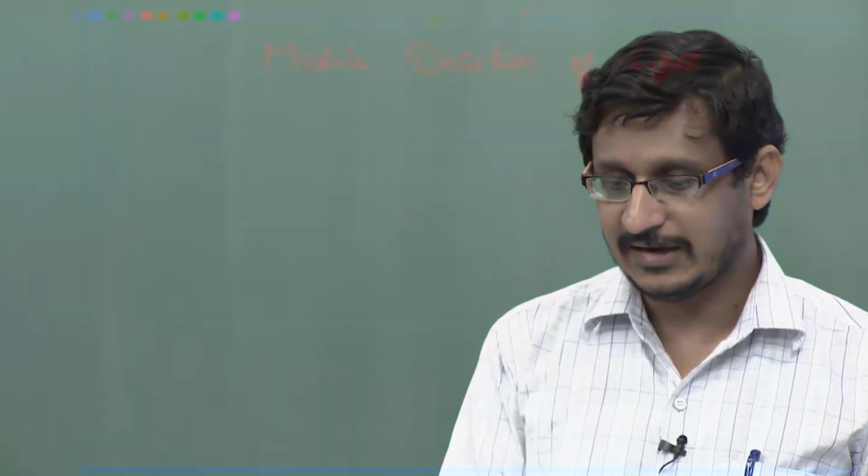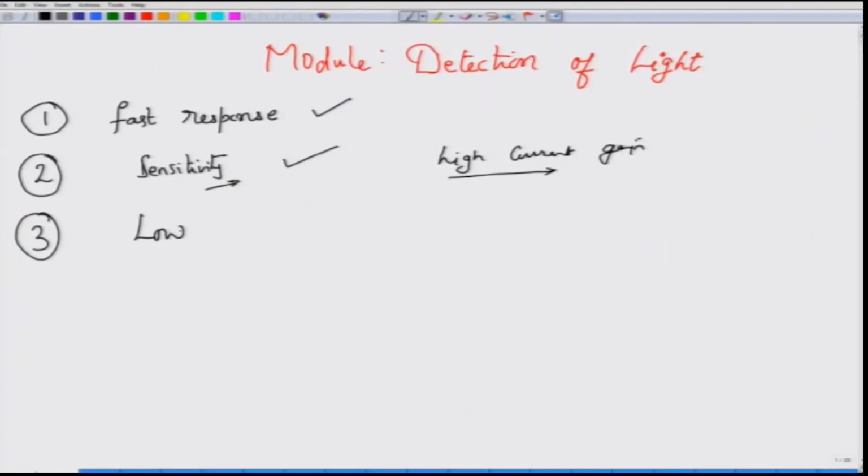So one of the characteristics that you want from a photodiode is that it must add very little noise. Low noise is one of the important criteria from the noise perspective, because if my photodetector adds very low noise, then I will be able to take the optical signal at very low powers, yet have sufficient signal to noise ratio at the output in order for me to detect information sitting in my desired signal.